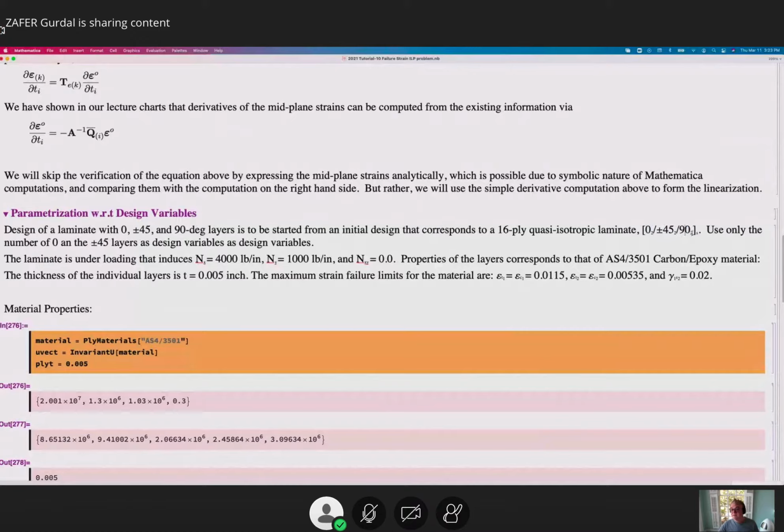I will change the space, the laminates, a little bit. I'm going to make this M and N. So I can try 0, plus minus 45 subscript 2, or 0 subscript 2, plus minus 45. Two variables, M and N. Only one layer of 90-degree ply, and a symmetric laminate. In fact, I may want to enlarge those texts later on a little bit more.